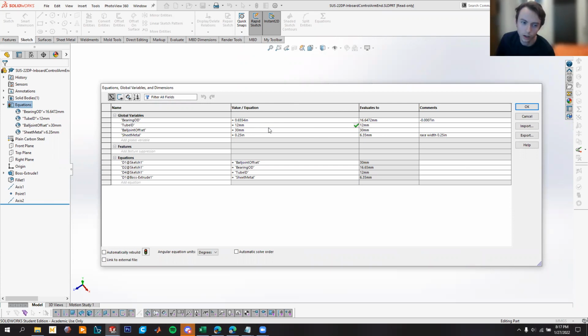These are parts that we can fillet or chamfer using a bench grinder to get some curvature on those corners. So 0.495, so we'll go like 0.485 inches. 12.39 millimeters. Just call it 12 millimeters.